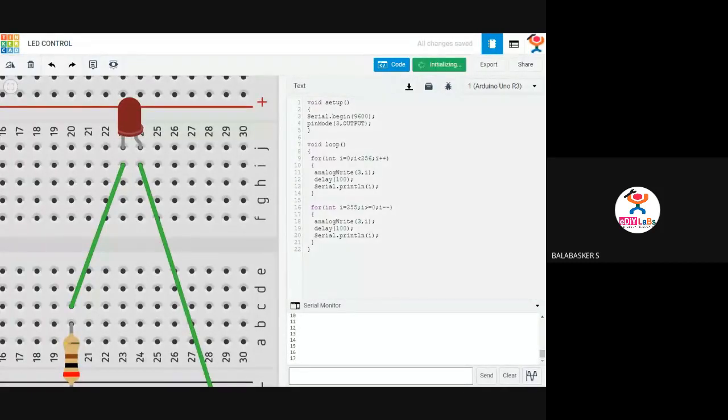Again I am running that value. Now you check. Now the light will be slowly glowing on. So my value is around 100, 150. It goes on. So once it reaches 255, it again decrements, and the brightness of the LED will be reducing. See, the value is getting decreased, the brightness is also getting decreased. Once it reaches the off condition, again it will be increasing.